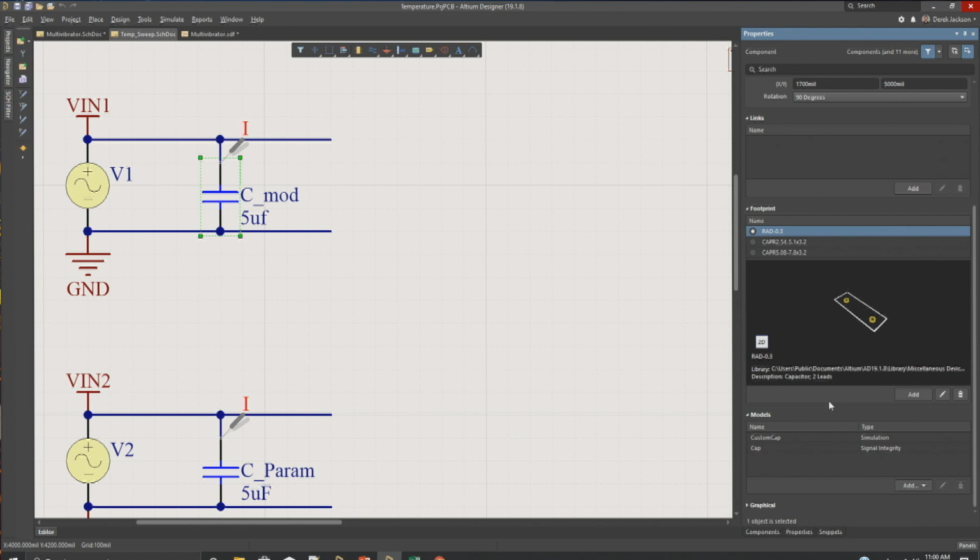A lot of manufacturers used PSpice's really good model generator, which is why, when you download from the manufacturer, they'll have PSpice and Spice 3. You want to grab the Spice 3 model.